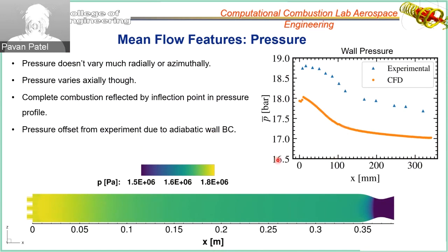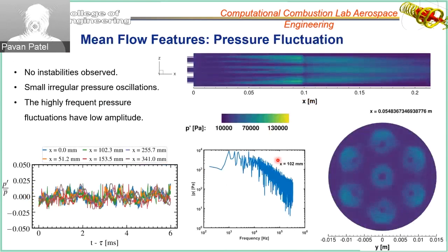So this is just the pressure profile, and the pressure profile is really important to validate your numerical study. If you can match the pressure profiles, you can really tell what's happening inside the chamber very well, and you can explore what the experimental group probably couldn't find because they cannot put probes at every place in the chamber. And something that's important is also the pressure fluctuation.